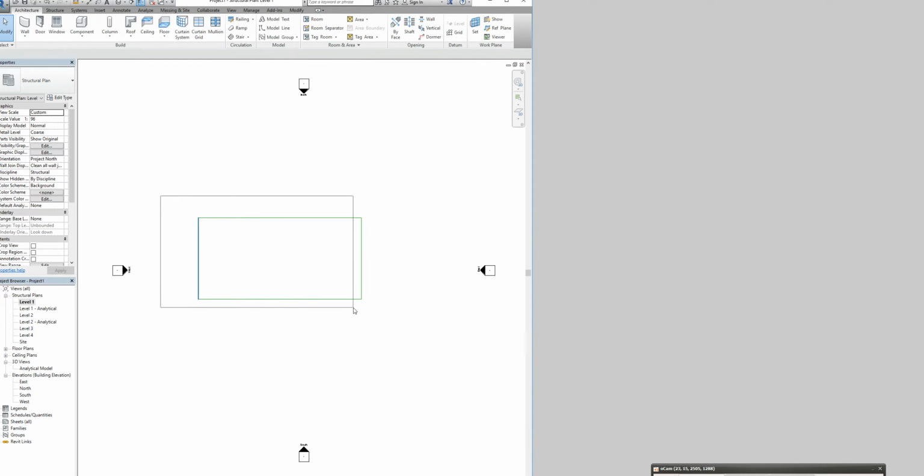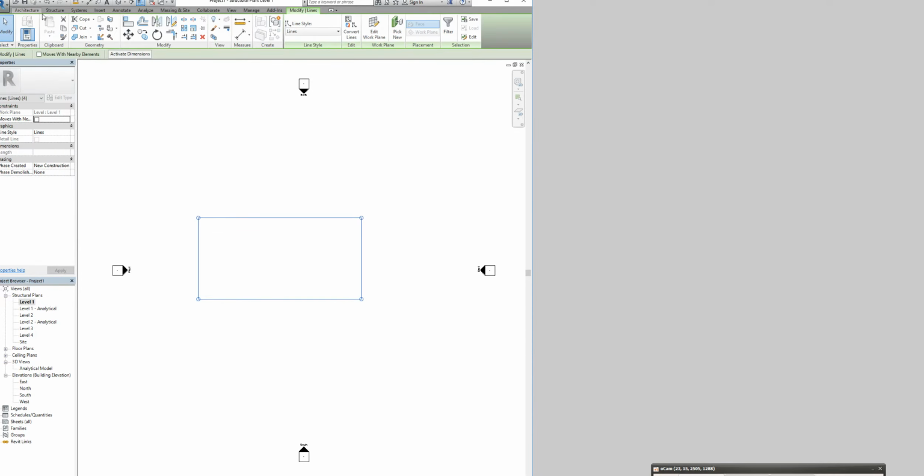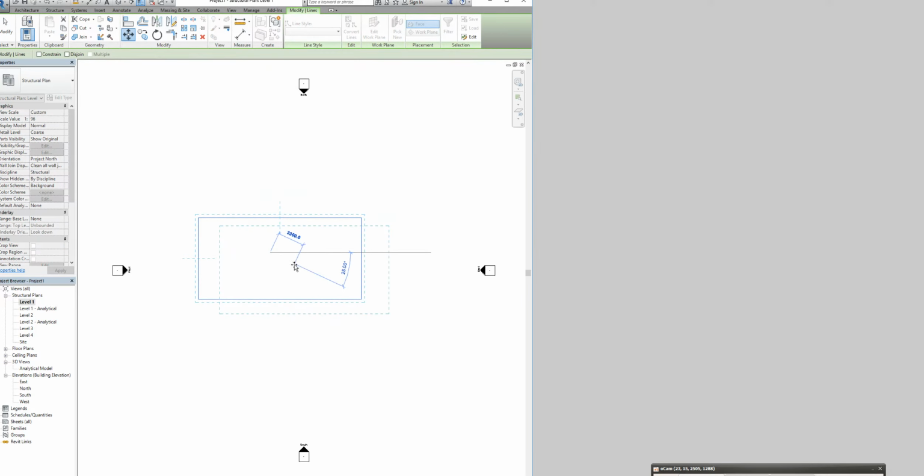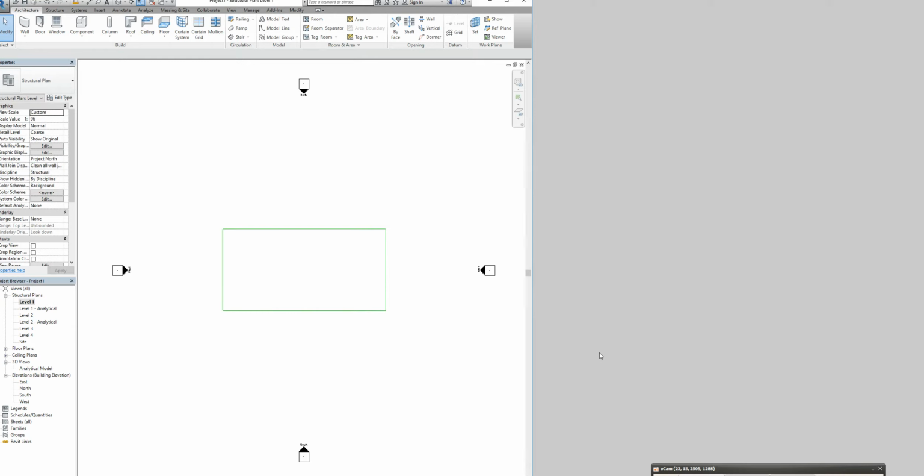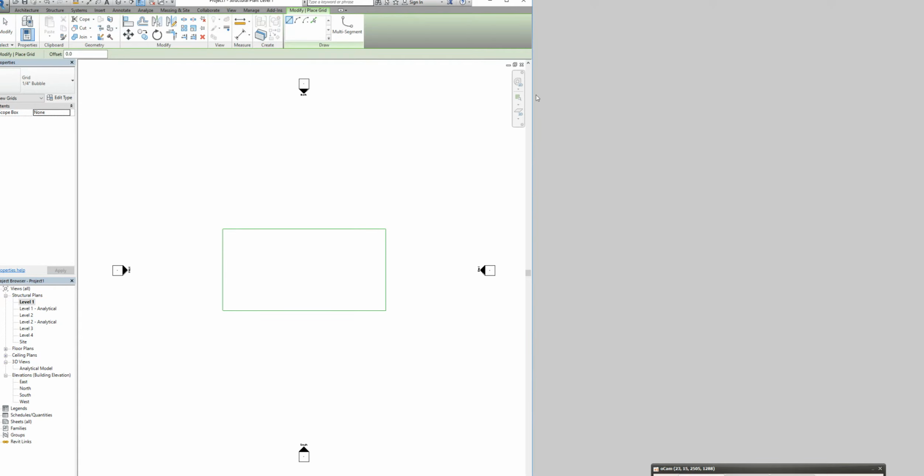All right. My particular preference, I just drag this to the center of the screen. That's just because I like to work like this, so it's not described in the slides. Next step, I go to Structure tab, Grids. Create one vertical and one horizontal grid by using Pick Lines command. So go Pick Lines here and here.